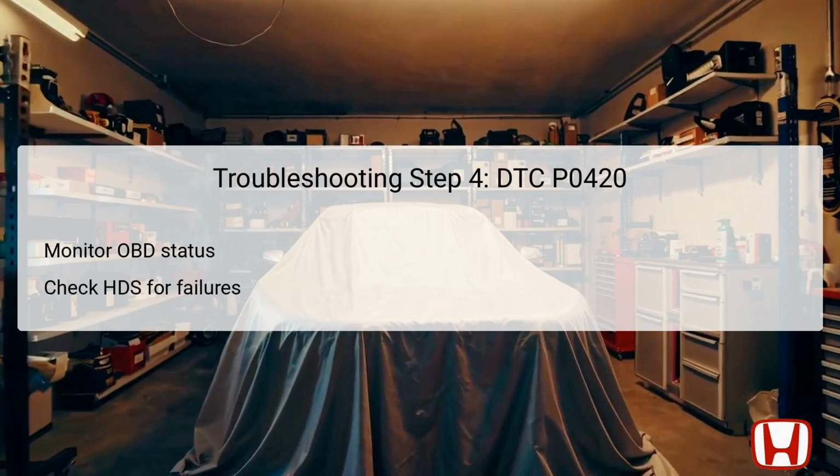If indicated as executing, it means you should keep driving the vehicle until a definitive result surfaces. If the HDS reads out of condition or not completed, return to the previous step and recheck the specified driving conditions. This step is crucial as it determines the migratory state of the error code.